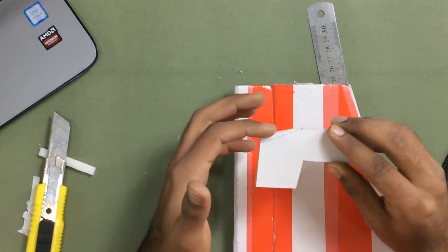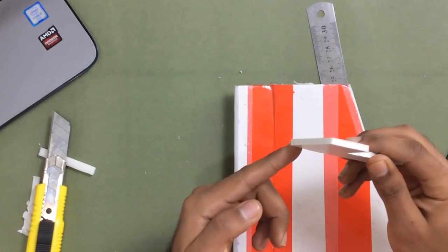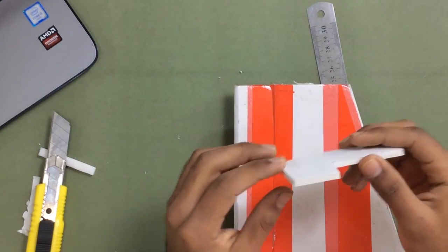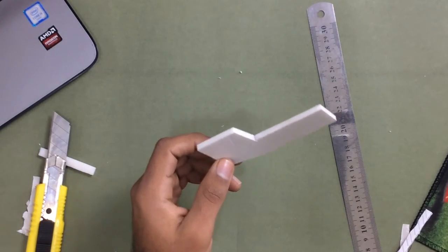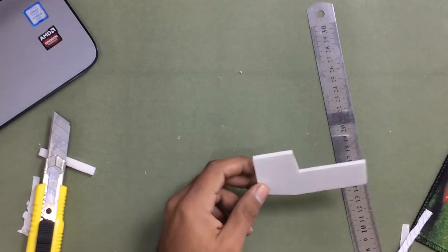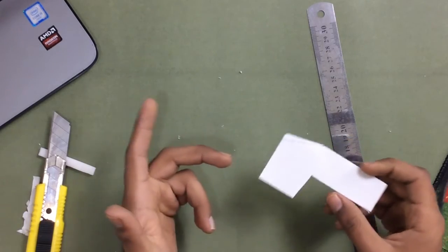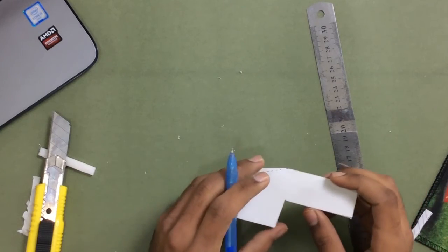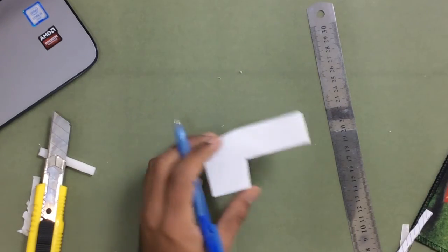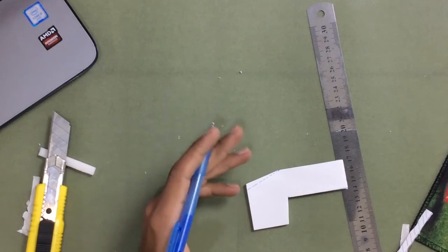The first one is 13 degrees, and the next one is 18 degrees. That depends upon you if you want more throw and more sensitive controls. You can go up to like 20 degrees, but more than 20 will be excess for this kind of plane, like trainer planes for beginners.